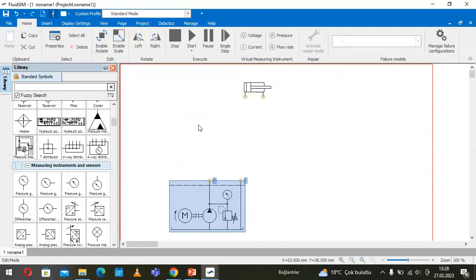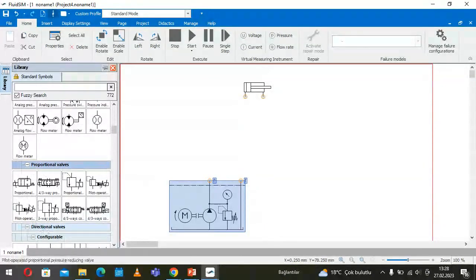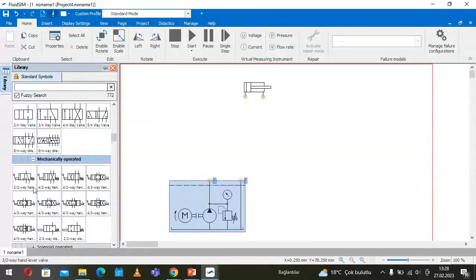As I said, to drive the cylinder, we learned already that we have a 4/2-way valve like this for the double acting cylinder. For the single acting cylinder, we use a 3/2-way valve. So this is the valve we can use to drive the double acting linear actuator. This is the pump side, which we have to connect to the pump, and this is the tank, which has to be connected to the tank like this.